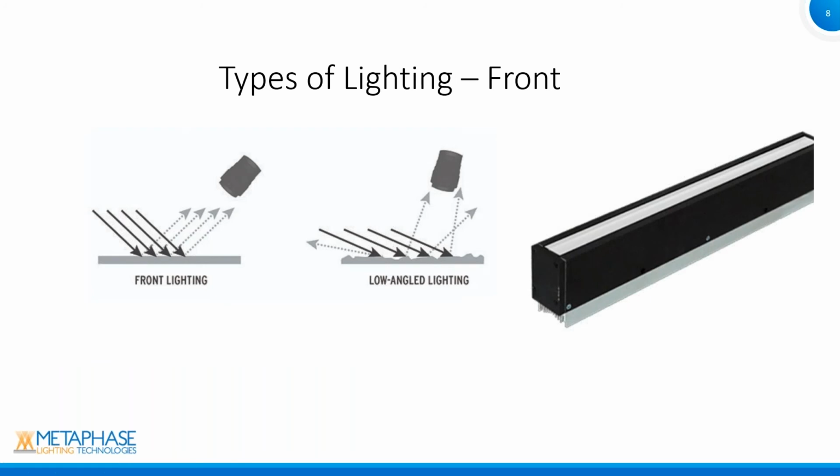The big analog that we have with area scan and line scan is the fact that many of the lighting formats and types and processes are the same. So just like with an area scan, if we had to illuminate a given size, we would use front lighting. And the same thing goes for line scan as well. Except instead of trying to illuminate a 2D area, we're really only illuminating a thin, quarter of an inch line incident on that surface. And that is what your camera is going to be looking at as the material passes across it.